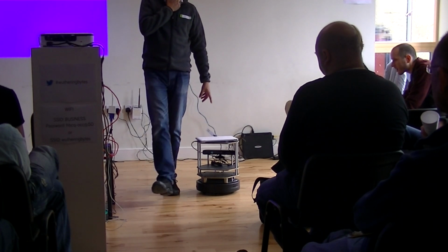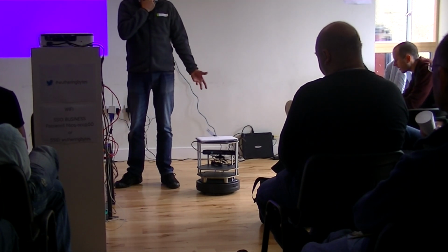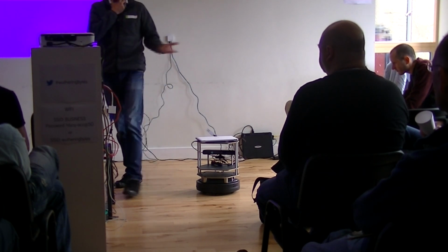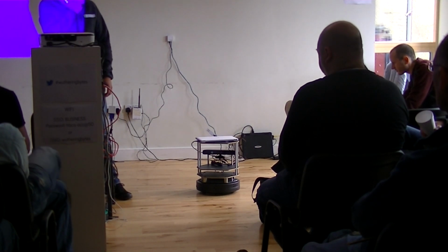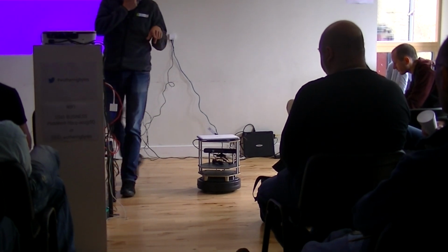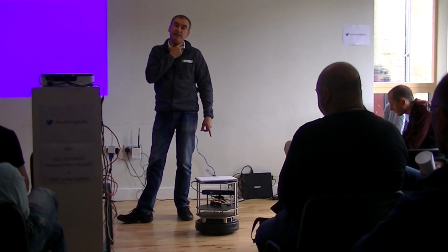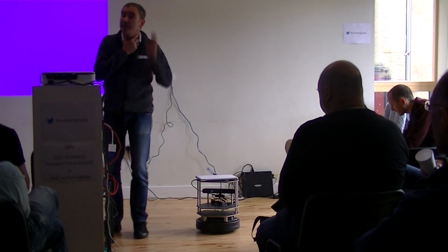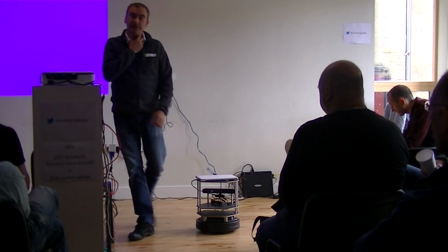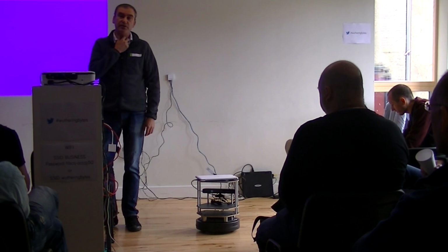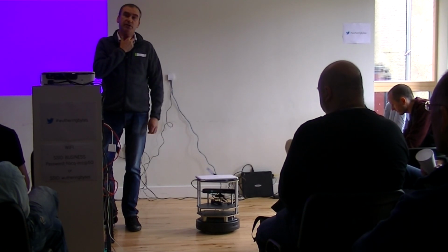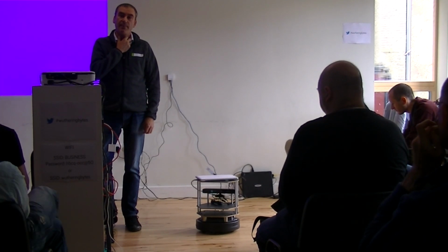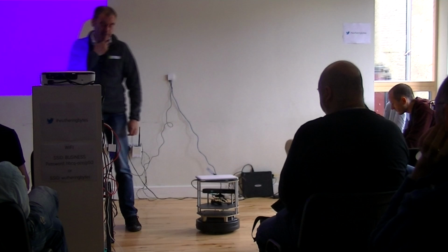If you want to talk to the Kinect, yes you do, because I don't know that anyone's got the Kinect working with the Raspberry Pi yet. The USB doesn't work well. Yeah, USB, the last time I saw it, they hadn't done it. But you can run ROS on a Raspberry Pi, so if you were just driving the robot base, you could do that. But if you want to do the camera vision stuff, a BeagleBone would probably work. BeagleBone is a better platform for it. Somebody worked on Google Summer of Code getting it working on BeagleBone. We weren't using a Kinect, but we're using a similar webcam. We've done something kind of similar.